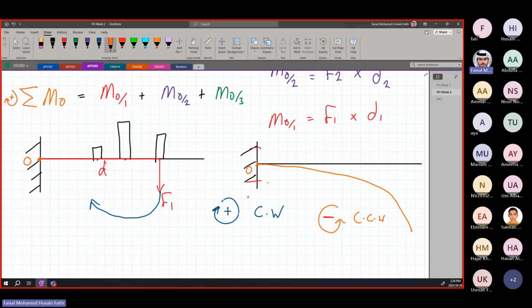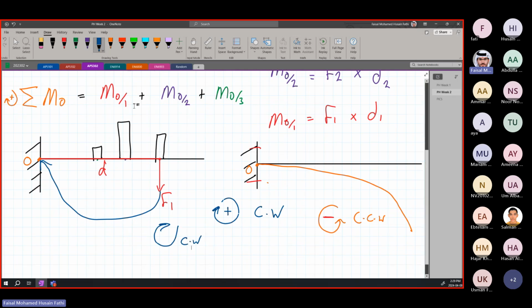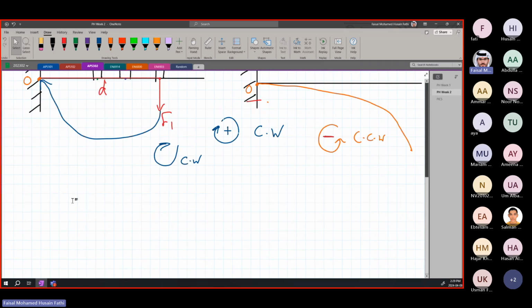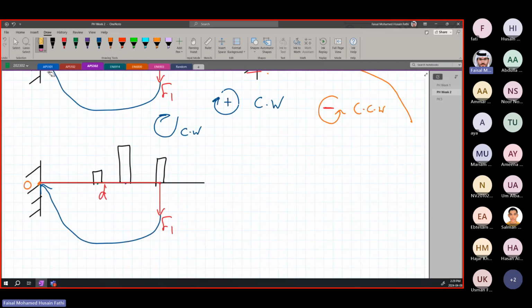So how did we know that F1 is clockwise? Because again, we are going to take the arrow, and we're going to try to spin it towards O, as if we're trying to connect it to O. We are looking at which direction it is going. It's going into that direction, so it's in the clockwise direction. And we're going to do the exact same thing again for each and every one of the forces. All right, so that was for the first force. You will notice that they're all very similar. This is F1. We are done with F1.